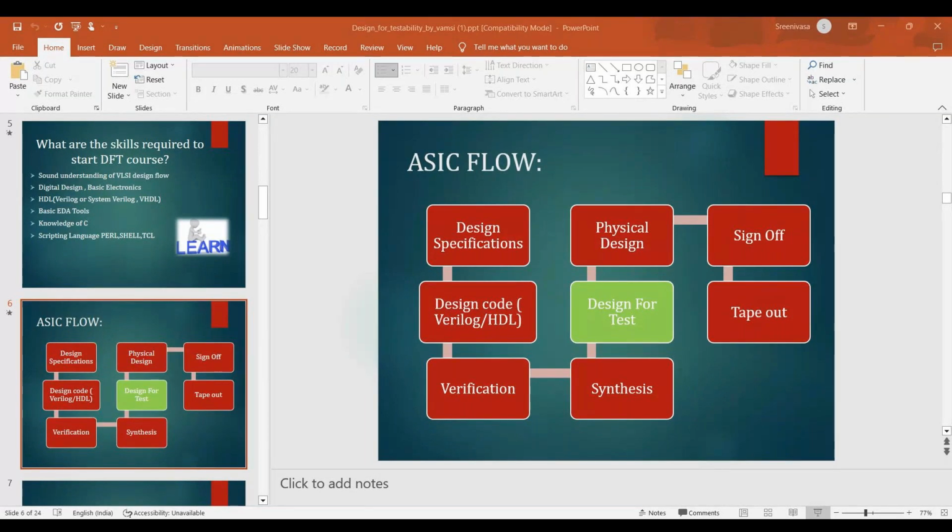Now, in this whole phase, why should I add an extra design? I have clearly mentioned earlier, right? When you have a chip which is already designed for the specification, we add an extra design here, which we call a DFT. This is an additional design which is placed inside the chip. Why do we need to do it? If you don't have your DFT logic in the chip, what happens? Why can't we test the chip without the DFT logic? We will see that in the coming slides: what is meant by DFT, how it is important, and why it is used for testing.